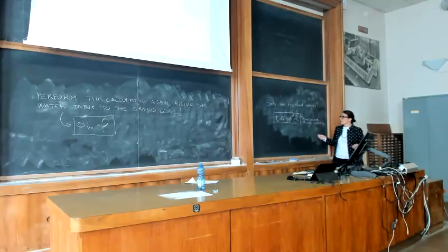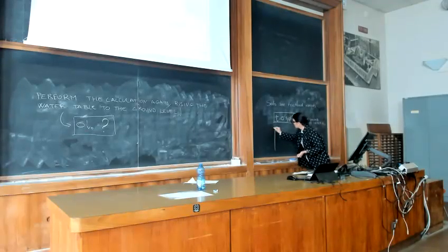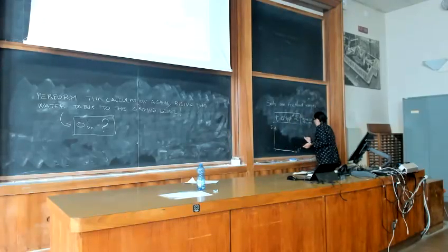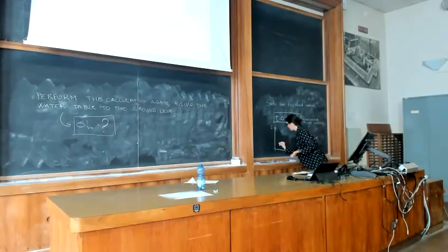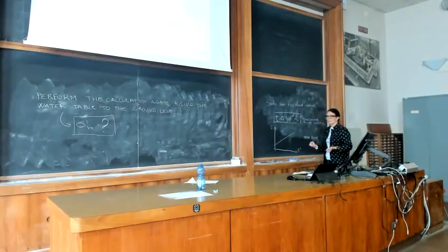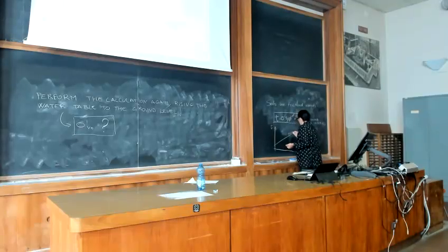This is easy. What is not easy is the real soil behavior, because this is a scheme. We will discuss this more in detail, but if we adopt the Mohr plane for the representation of the shear strength of soil, you know that this criteria basically is a line. This is the failure envelope.